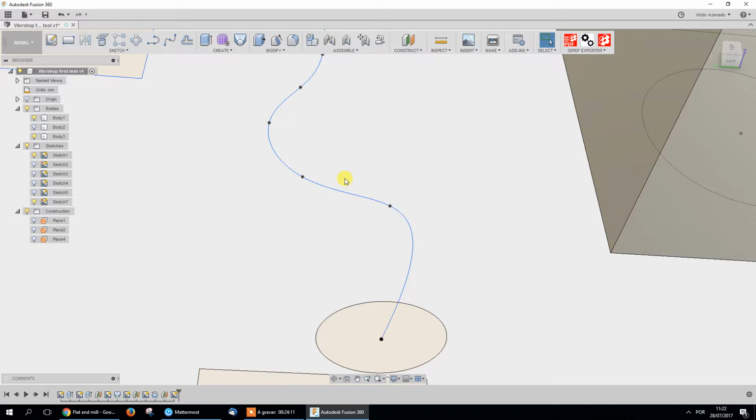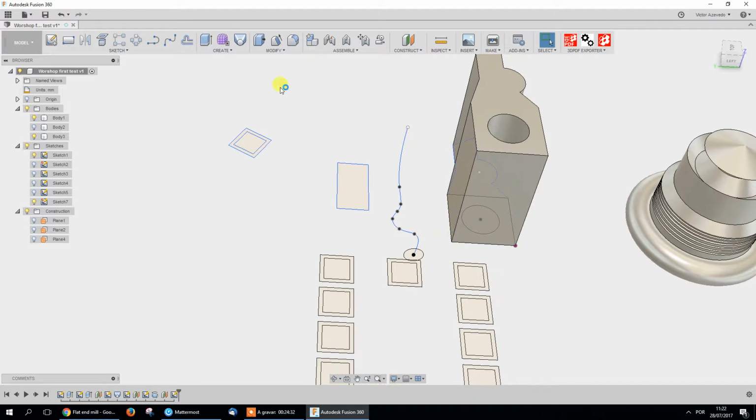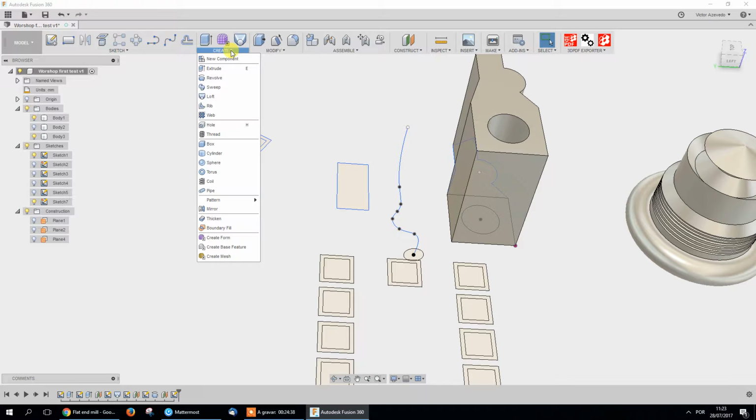So it doesn't know where to track the path. That's why usually we put it on the ends of the path. The sweep can be used to create different paths with the same profile. Also useful, maybe to create a wire for some design.